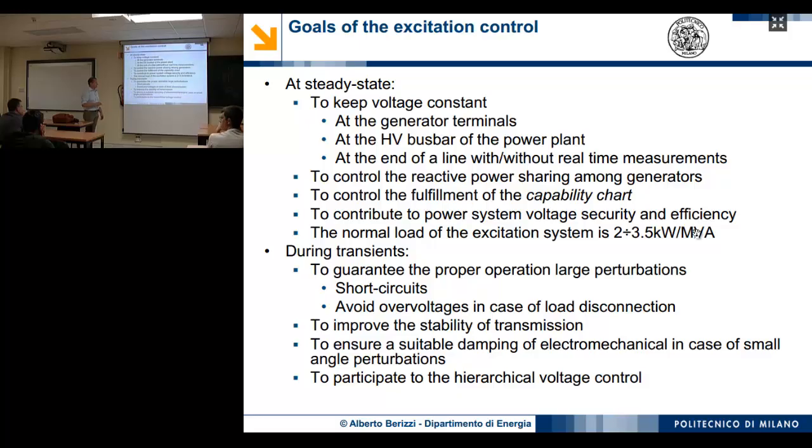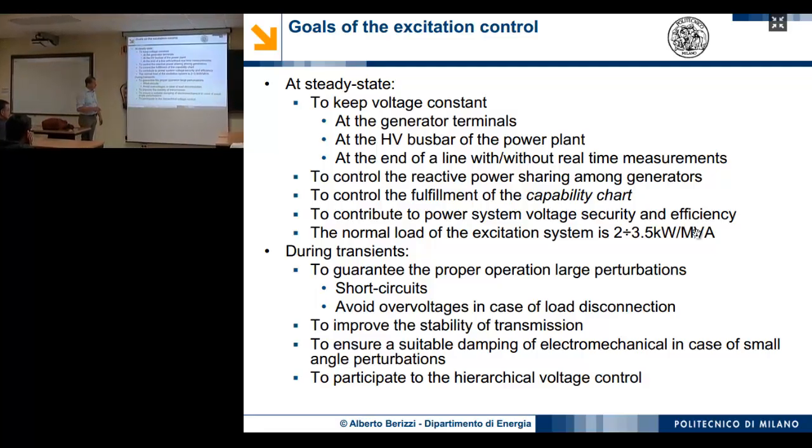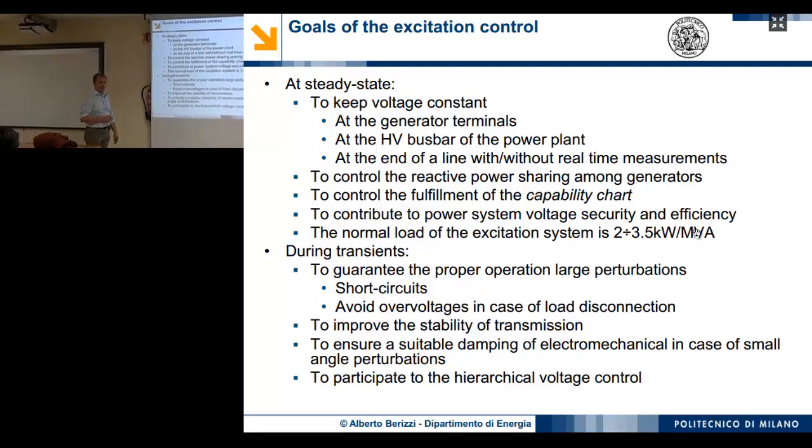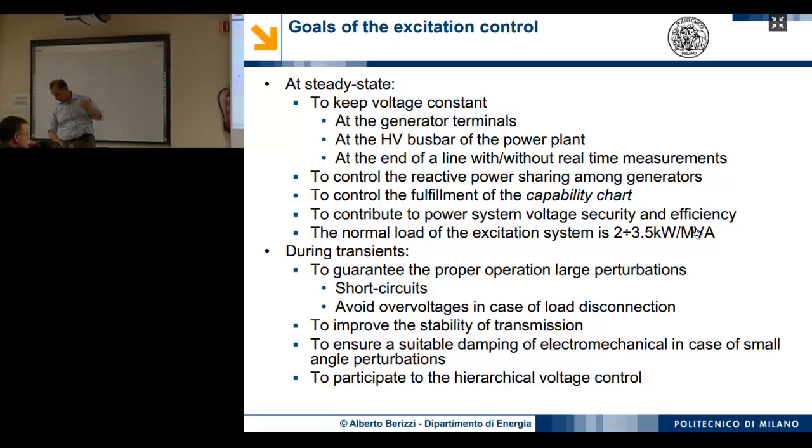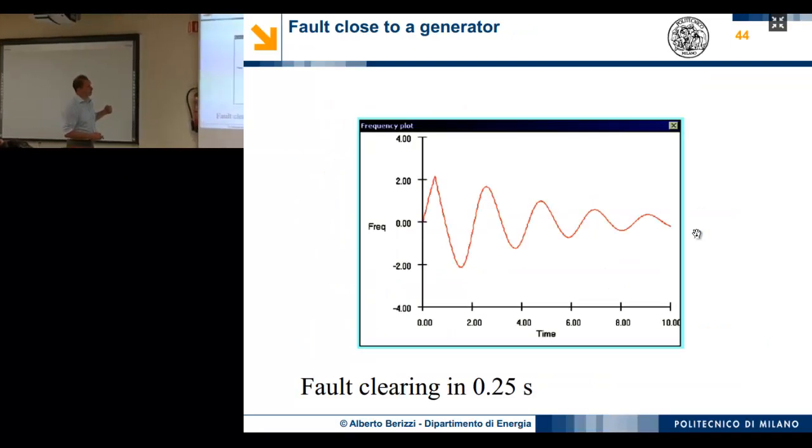Avoid overvoltages in case of load disconnection. Okay, some other. This is important. Improve the damping of electromechanical oscillations. So you see that the excitation control is very complex and has a lot of different goals.